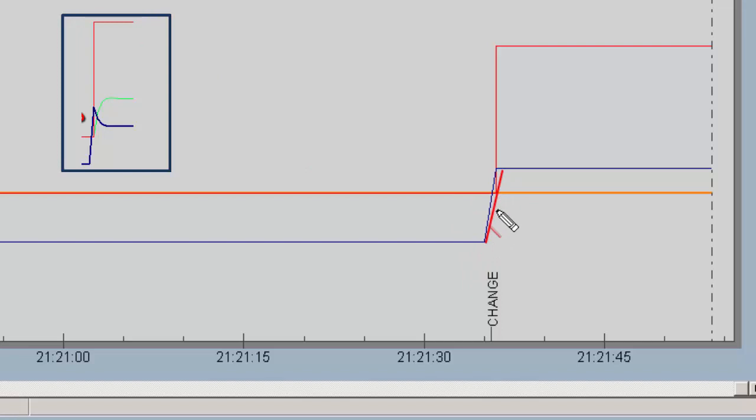But now because the valve is stuck, the PV stays constant. And because the PV is not changing, its velocity is 0. And the error at this point here, the velocity is also 0. The change in the output is 0. So your output doesn't move at all. So that gives you an indication of how this differs to when the valve is not stuck.